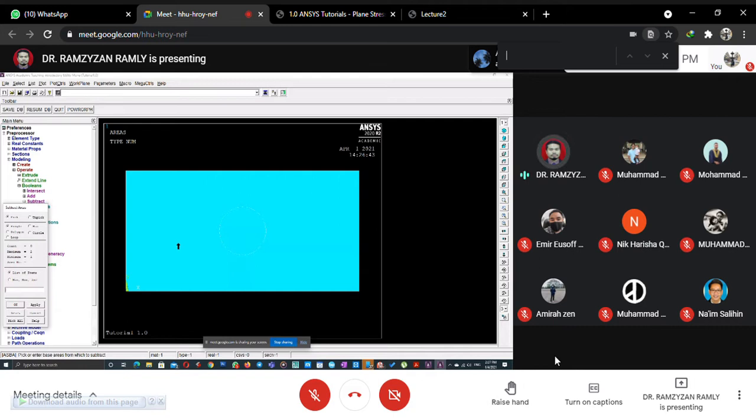Okay, a pop-up menu will appear. We have to choose which one is the main one first. Okay, the main thing, the big thing that we want to deduct from. All right, we are picking the rectangle. Okay, a notification appears. There are two areas at this location. Pick area 1. Okay, press OK. Okay, and then we pick OK.